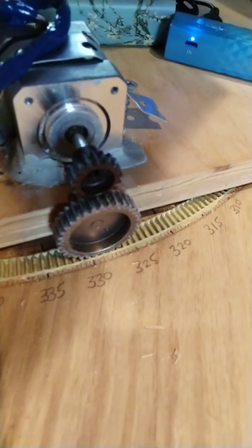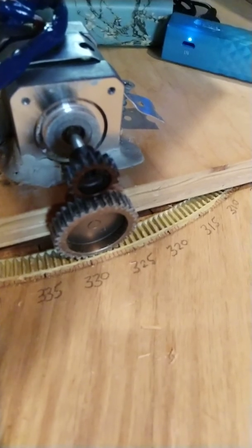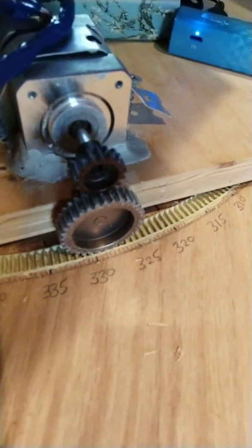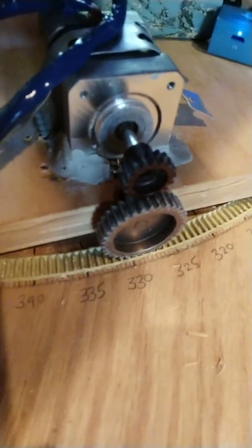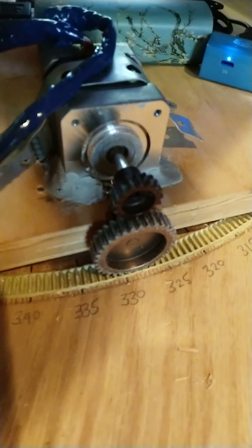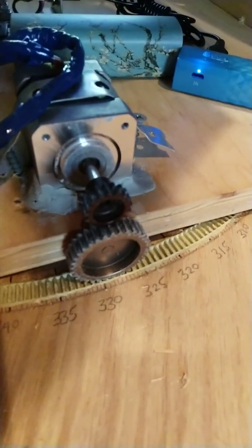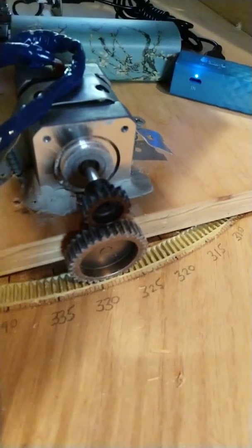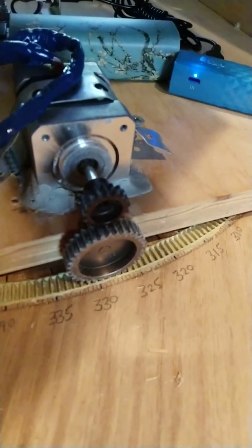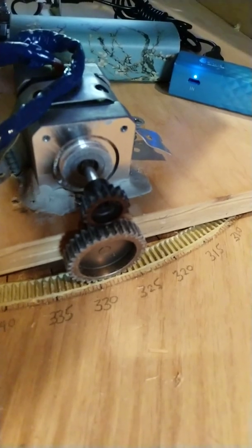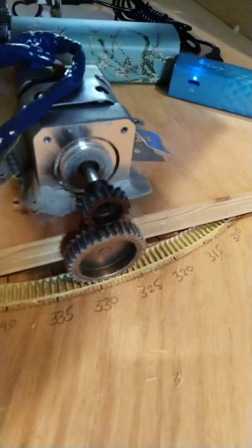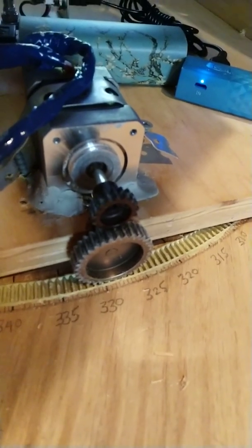This particular one here is called Milliput, and I pushed it in all the way around, let it set for about an hour so it wasn't as sticky, and then set the rocker box back on top of it with the gear already mounted. And so the gear pressed into the putty, and then I just spun it around in a full circle, and the gear itself made the track, the teeth mark for the bottom gear.